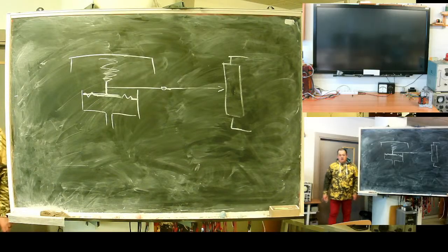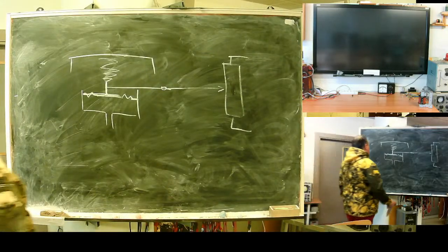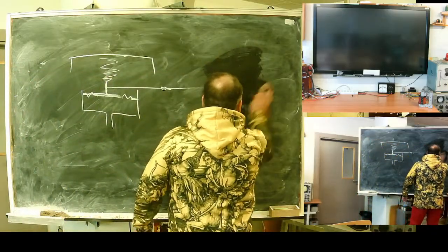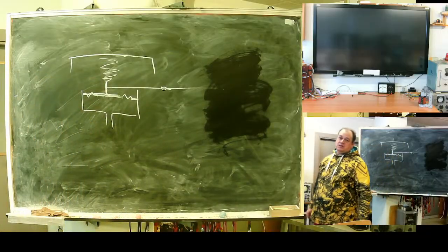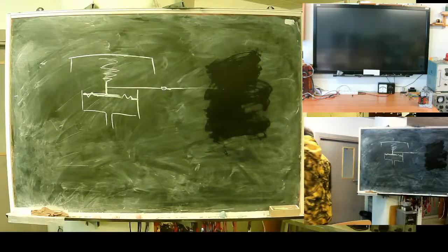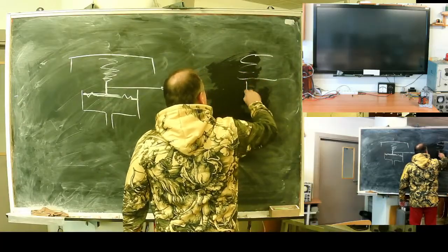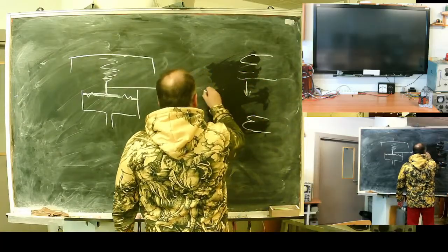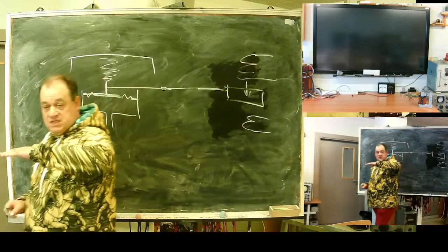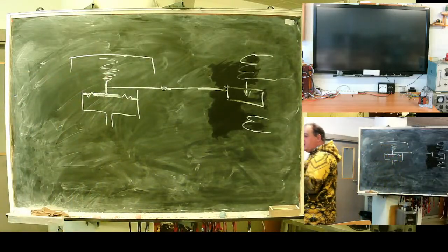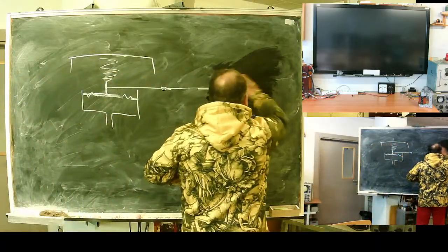For a rare case, an array of optocouplers can be used. But one of the tricks that can be done is usage of a magnetic sensor based on mutual inductance: sending coil, receiving coil, kind of screen disrupting the flux. Not precise. Good idea, working idea.